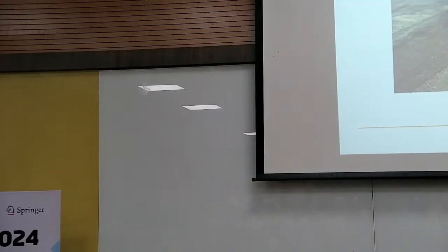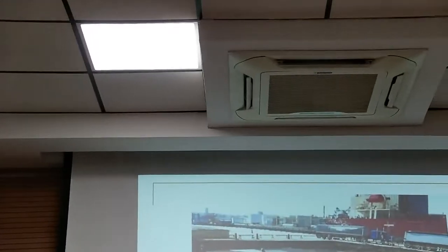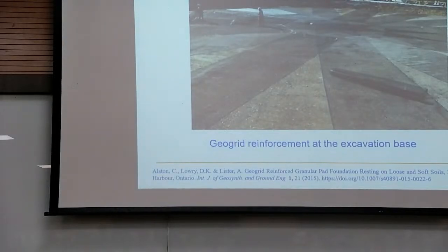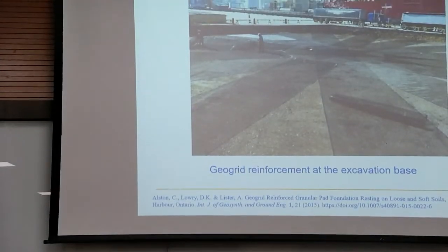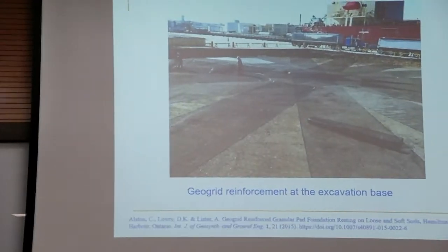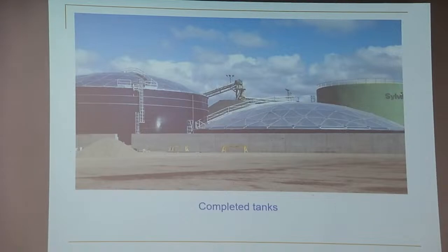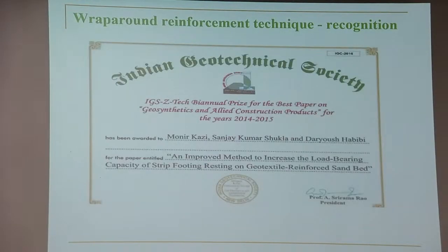So, and this is a field project. You can see in Canada, there is a full case study of how they avoided deep foundation. They avoided it just by reinforcing the foundation using geogrid, in a harbor, coastal area. And this is the finished product, completed tanks.